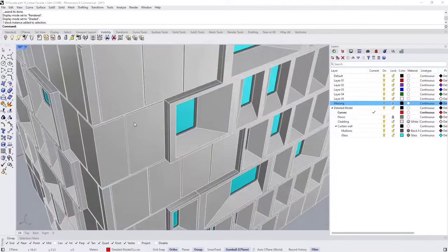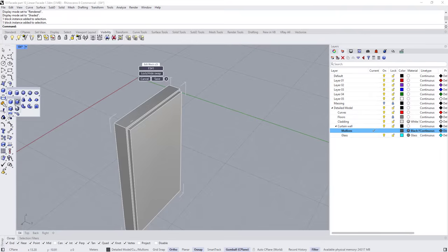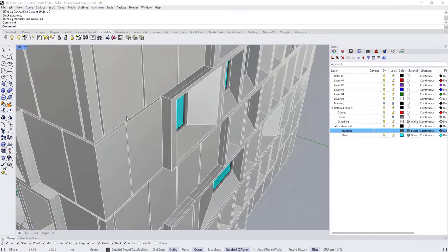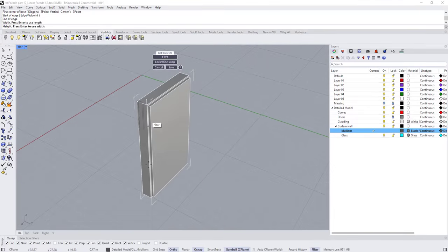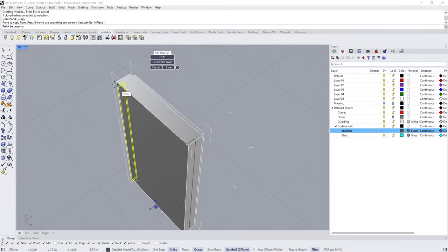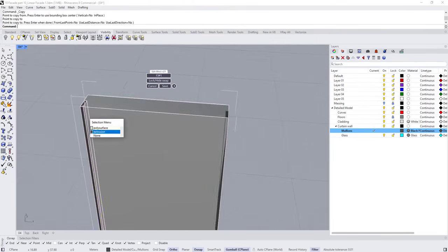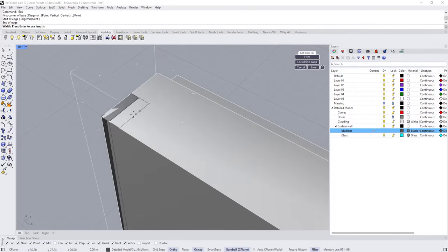Okay, now I'm going to edit this part. So let's come here and select the mullion. Let's draw, oh, sorry. So let's choose 3-point box. Let's do a mullion here, maybe 0.2 and 0.05. So we have a mullion here. Create a copy. Another one here. And another here.